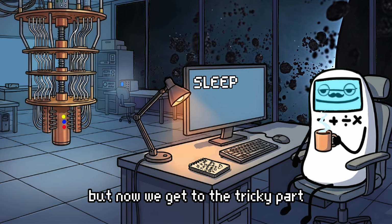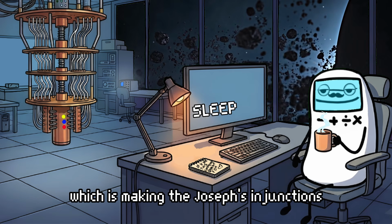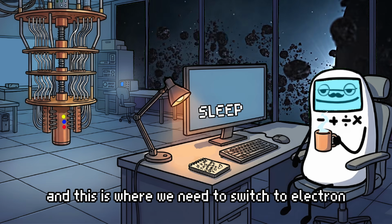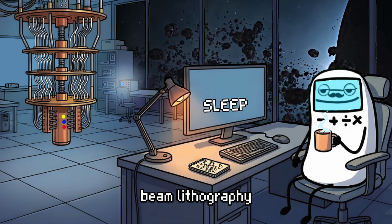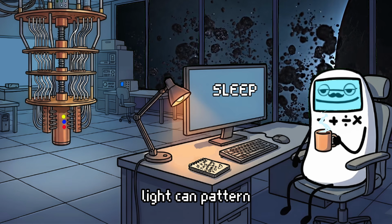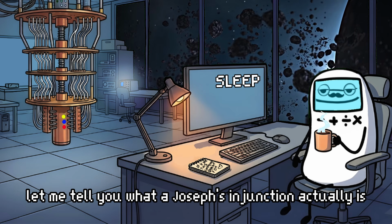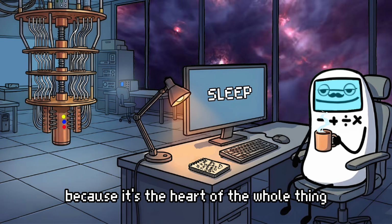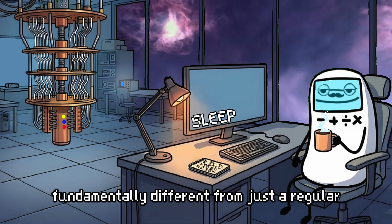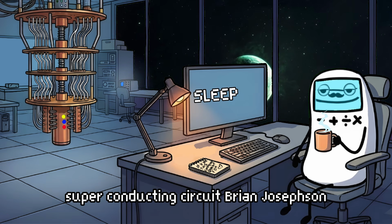But now we get to the tricky part, which is making the Josephson junctions. And this is where we need to switch to electron beam lithography because the junctions are much smaller than what UV light can pattern. Let me tell you what a Josephson junction actually is, because it's the heart of the whole thing. It's what makes superconducting qubits fundamentally different from just a regular superconducting circuit.